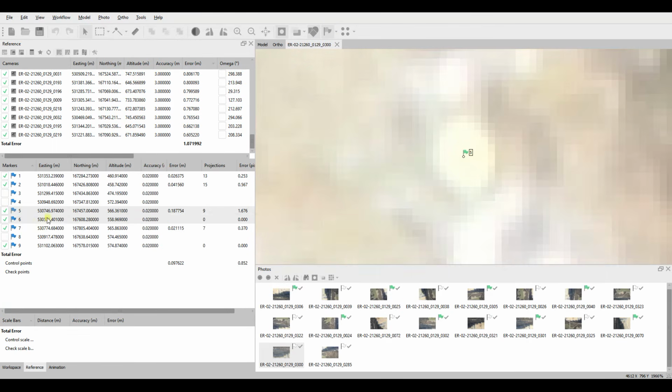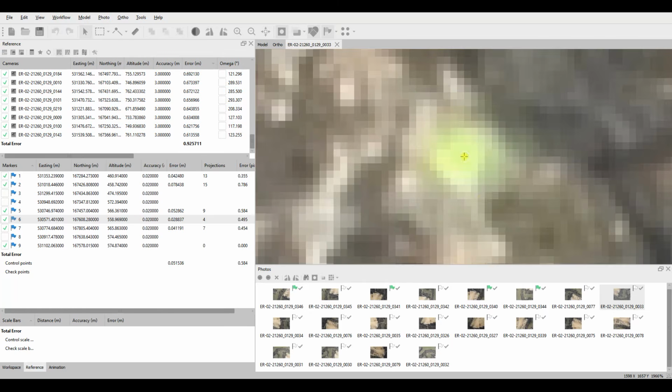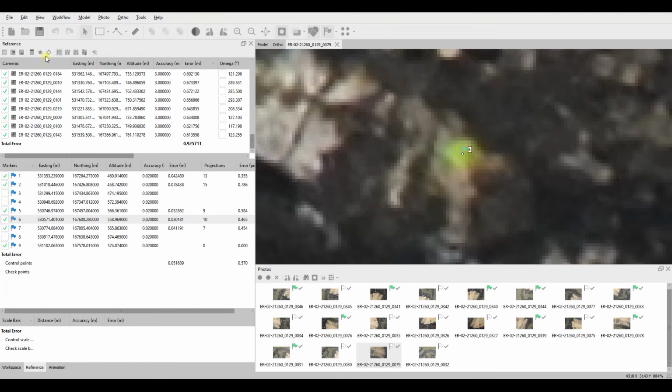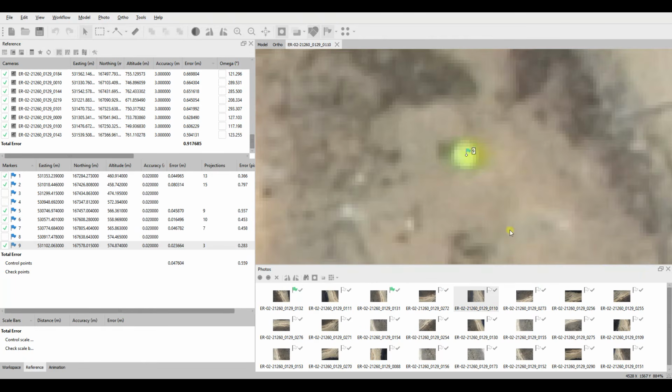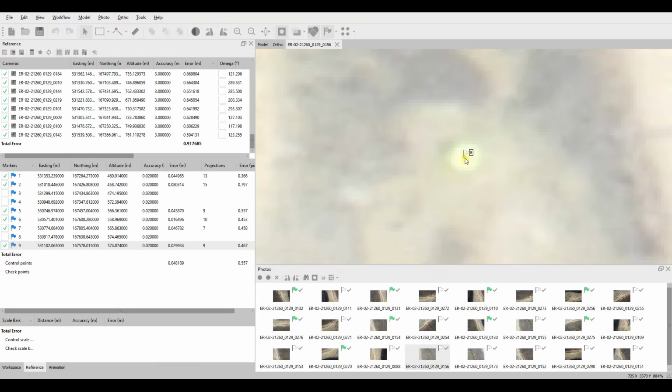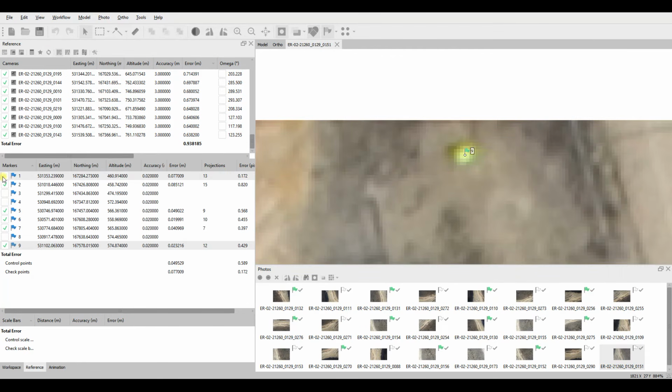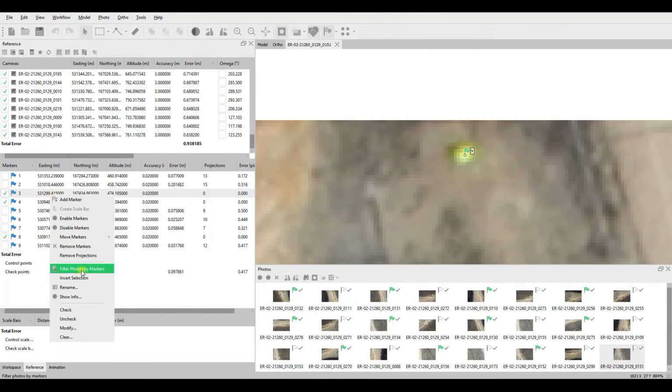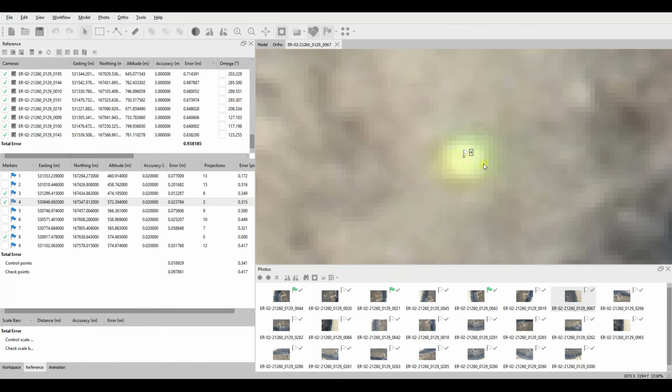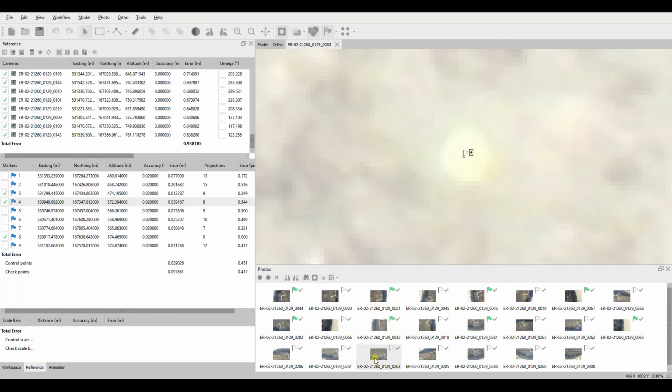And once you've got right to the end and you've done all of them, we then want to go back and visit the checkpoints that we've placed. So we still aren't optimizing the cameras. So change the selection criteria, go to your checkpoints, and now place the checkpoints as well. But in this case, you will not update the transformation and you will not optimize the cameras based on these positions, because again, we want them to be completely independent.